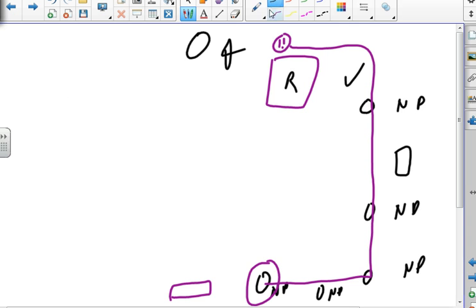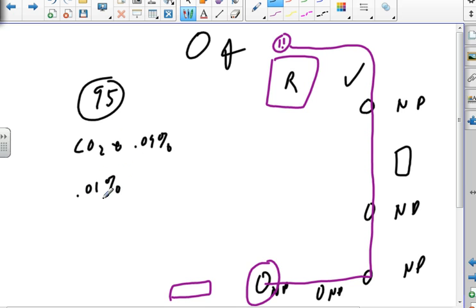So, up to about 95 or so, normal underway conditions on a submarine had CO2 about 0.09% of the atmosphere. And normal for human beings is a tenth of that. So nine times normal would be the normal on the submarine. You could get it down by going up and snorkeling, but we were in the middle of the Cold War, so we didn't do that. After the Cold War ended, we changed our rules, and we snorkeled for an hour every week, whether we needed to or not.